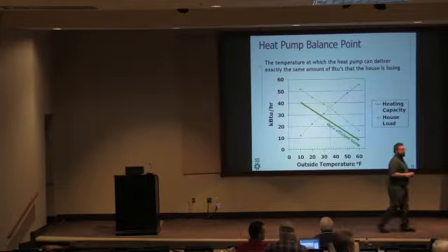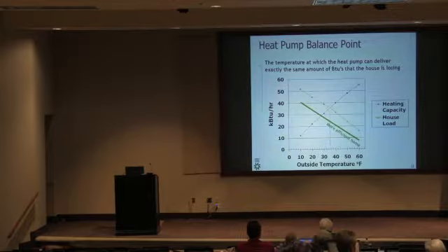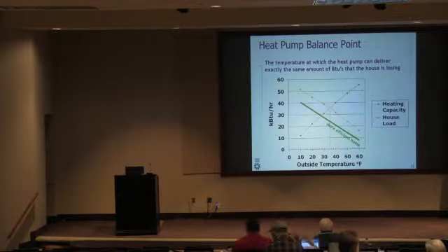The problem with some of these super high efficiency air conditioners, with larger coils and stuff, is they're taking a lot more sensible load than latent load, and they're just not taking out more moisture. Yeah, I mean, that's, again, it ain't the heat, it's the humidity, dealing with that moisture load. And our climate zone is really the primary comfort factor because just about any equipment, most of the time, is going to be able to make cooling.